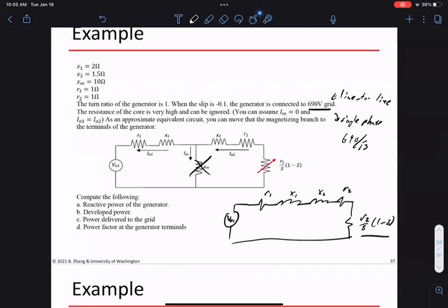That normally is very costly, because if you think of a big wind farm, there will be a lot of reactive power consumed by the generators. And typically our capacitors are not that large. Large capacitors are not super reliable, so we don't want to add very, very large capacitors to the grid. You do see capacitive compensation, but sometimes it's not cost efficient.